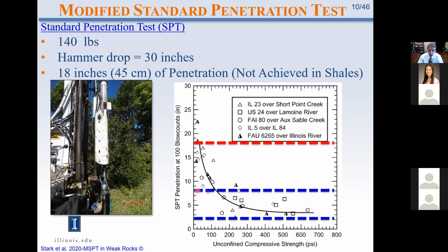Even if we use 100 blows with a 140-pound hammer, we had to come up with some meaning for running a standard penetration test that did not go 18 inches, frequently less than 5.